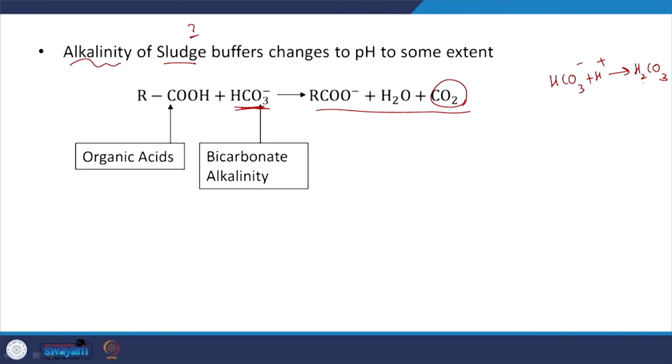So, I guess with that I will end today's session. One aspect to note is that with an anaerobic digester, you have to cater to the needs of the system, primarily with respect to pH, hydrogen buildup, and the methanogens, which are very sensitive to temperature. So, these are the aspects that have to be taken care of. In the next couple of sessions we will look at the other aspects, the different kinds of stabilization, and then more or less finish this particular course.